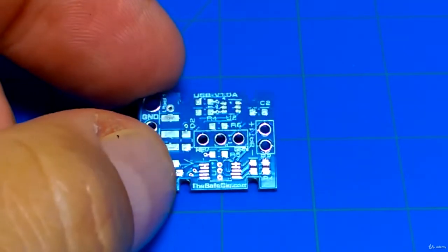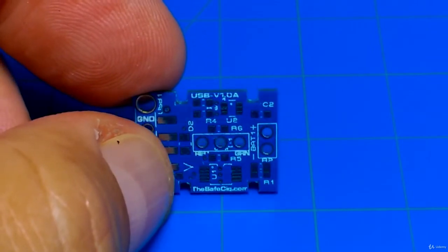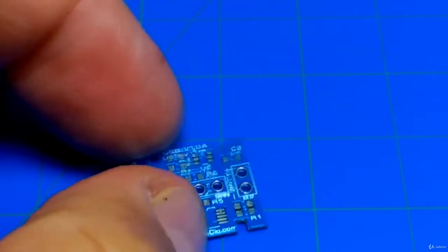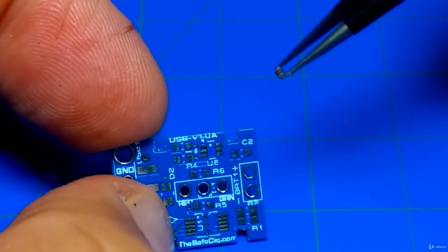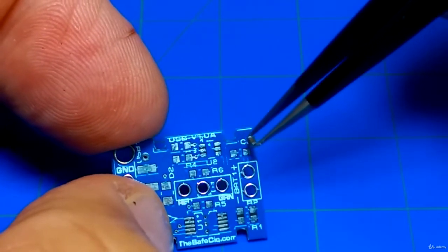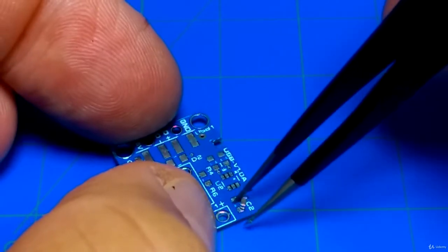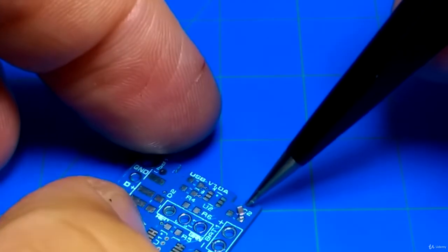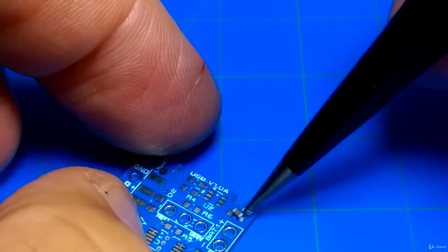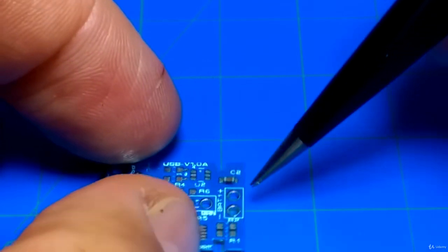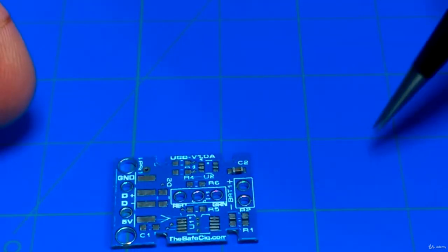And then when you're building something, let me get you another little circuit board here. Okay, so here's another little circuit board, and this is all surface mount. So this is a little charger that I designed, a little USB lithium-ion battery charger. So now, looking at this, here's the capacitor C2, and this probably takes a 603 size footprint. So you can see we just put it right on there. And so you would place it right on there, and one way or another, you need to solder that on there.